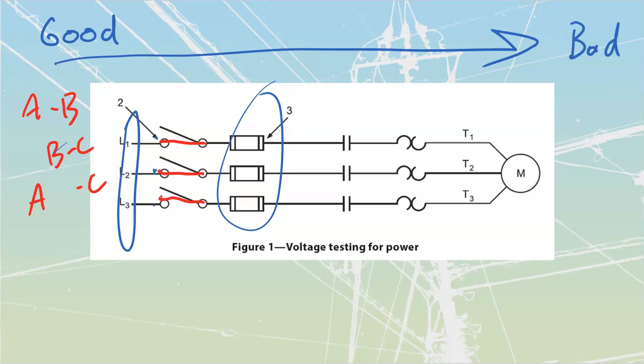They're not designed to be some Da Vinci Code level code breaking that you're doing over here, where you're having to puzzle something out. It's usually just a screwdriver that allows us to release that door, so we can release that door with those switches already closed in. You close the switch with the door closed, because the instant that you close in is your most likely instant that you would have any sort of an arc flash. So you contain that in the can, then you keep the door open.